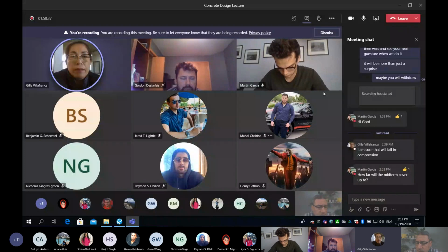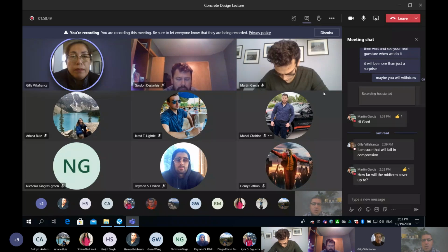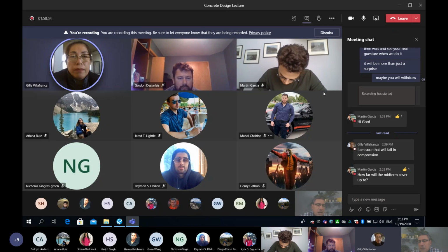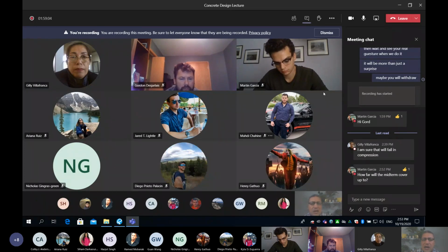Sir. Go ahead. Your first approach is changing the F prime C. And if that is still not working, we can always apply all the changes, right? We can try to change the width of the beam, right? Until we make it. To be honest, I'm telling you, the beam width and the beam height are controlled by the architect, and architects are not really easy because probably they have done their exercise. And why do they give you 600? Because it conflicts with other elements in your building.